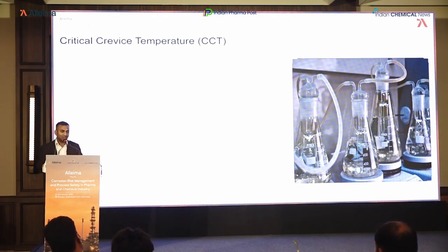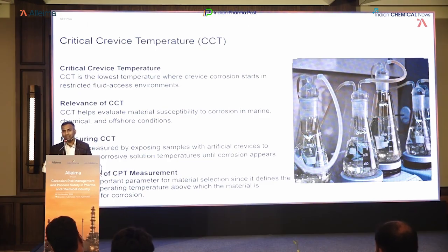And then comes the CCT. CCT is nothing but critical crevice temperature. Again, it is very similar to CPT. It is again dipped in a solution, but here crevices are made in the material and then checked at what temperature the crevices are formed.